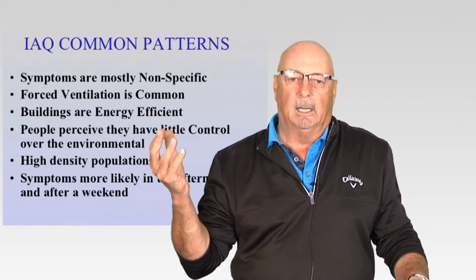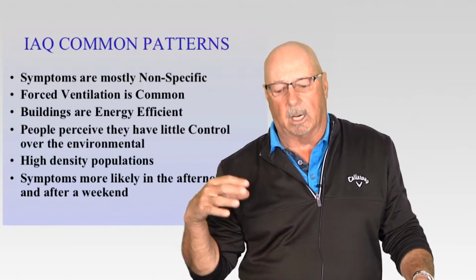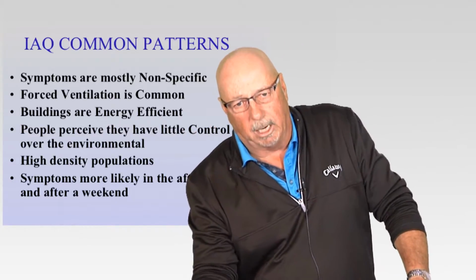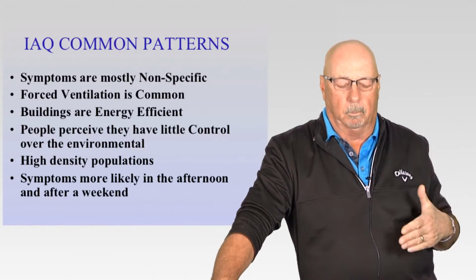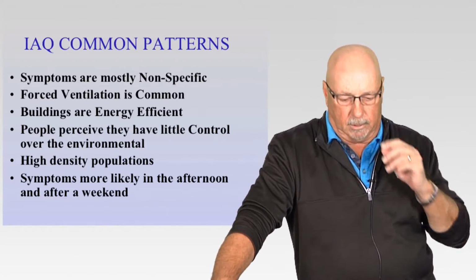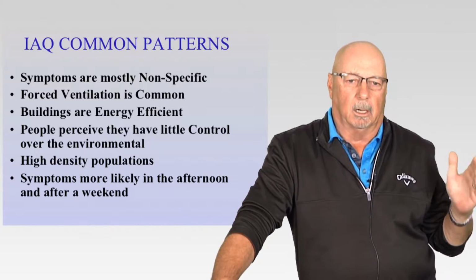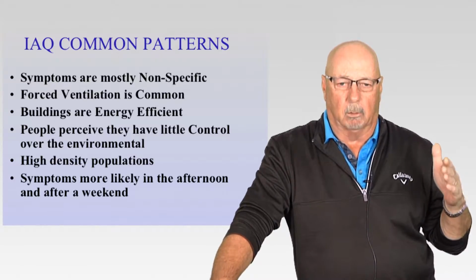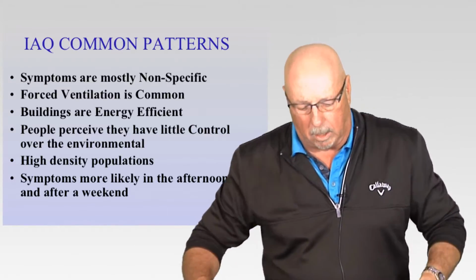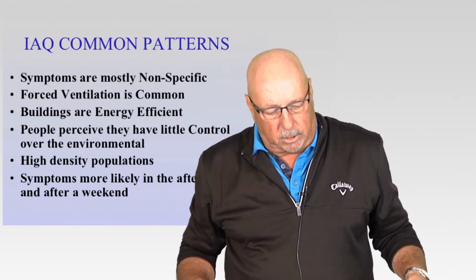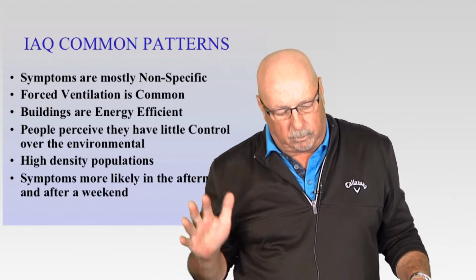They have a tendency to build the buildings to minimize the amount of outside fresh air being brought in from an energy factor, and therefore we don't get fresh air diluting down these contaminants that can be present in the indoor air. And because we don't have enough fresh air in there, these symptoms of indoor air quality will continue to happen until we do take the proper controls.